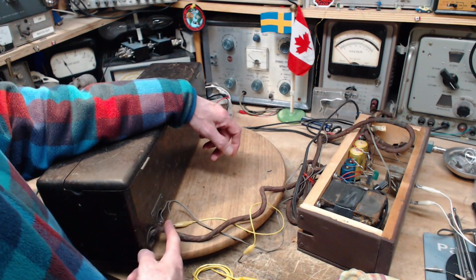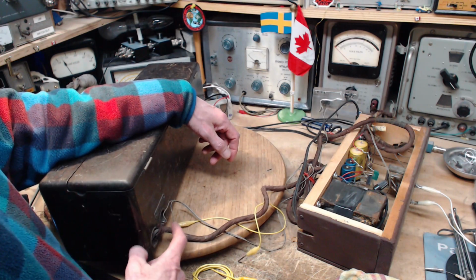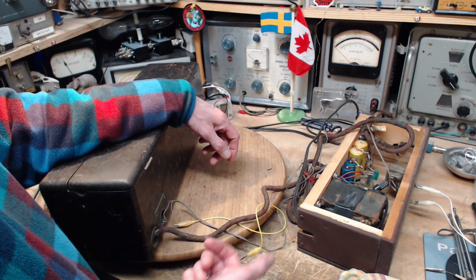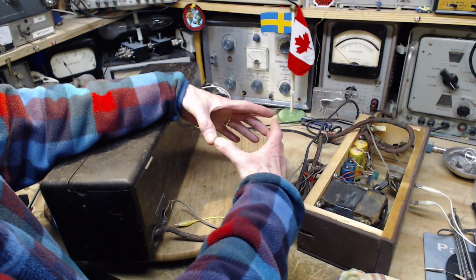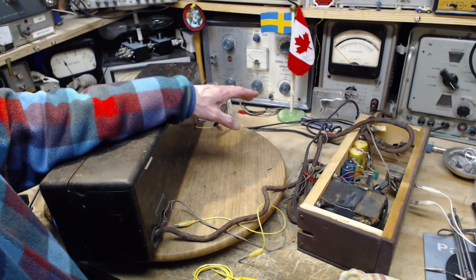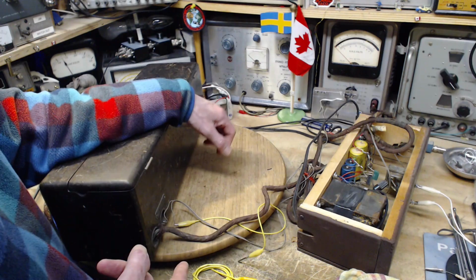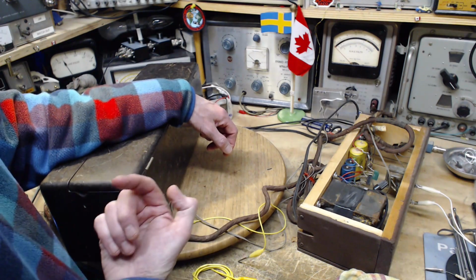The thing about the speaker output here is that it almost certainly has B+ on it. It's really looking for the kind of speaker I just showed you, that horn speaker with the plate on the piece on the bottom. That's a high impedance thing, and the B+ current goes right through the speaker.